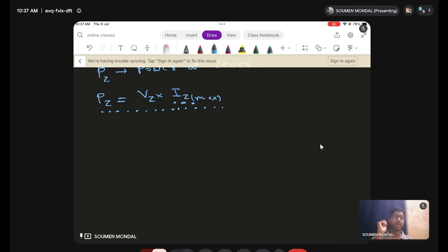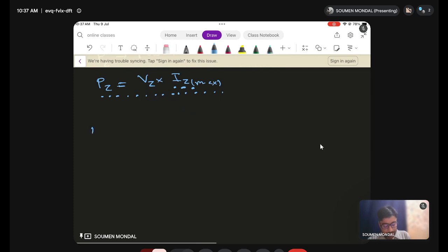If the Zener breakdown doesn't occur, then there is no meaning of this RS. Current will pass through RS and RL, and it is not going to disturb the Zener diode. Anyway, so the minimum value of RS in the circuit, so that we can protect the Zener.